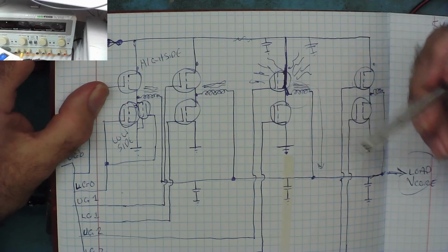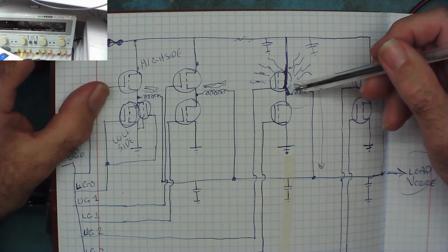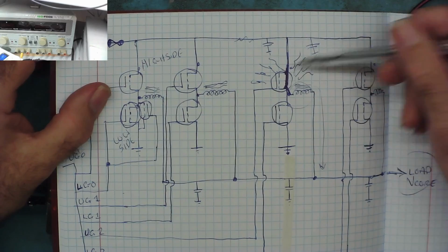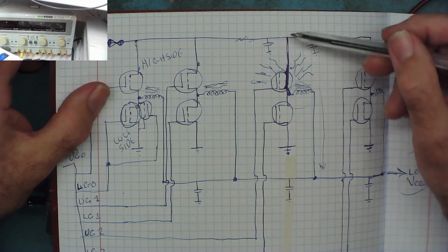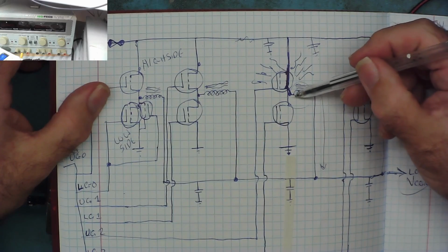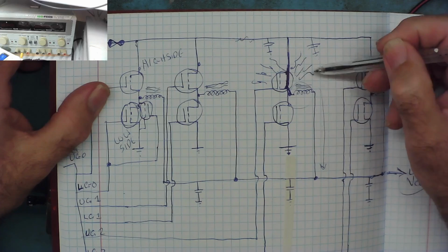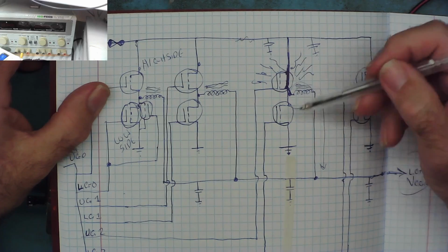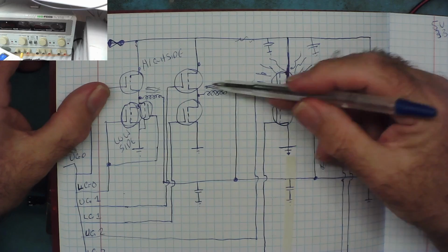Now, if I effectively pulse the current through here, which I'm going to do very simply by just rapidly touching the crocodile clip against the 12 volts, and I put an oscilloscope on this end of the coil, I'm expecting that the one which has the short circuit, I'll just see the voltage going on and off, but on the other ones